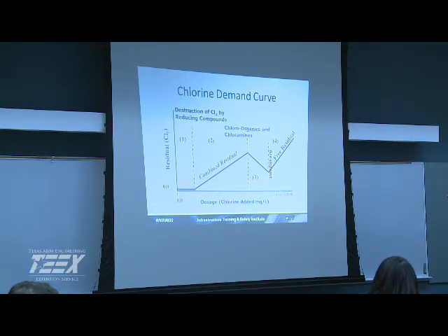you're going to increase your residual also. So a lot of times when people get in trouble is they're in that phase of 3 up in here, and they start backing off. Well, now they're going to have even more taste and odor issues. Yeah, it's counterintuitive, if you add less and you have a higher residual, you're not in the right area. You need to keep going. So that's a real important component of disinfection.